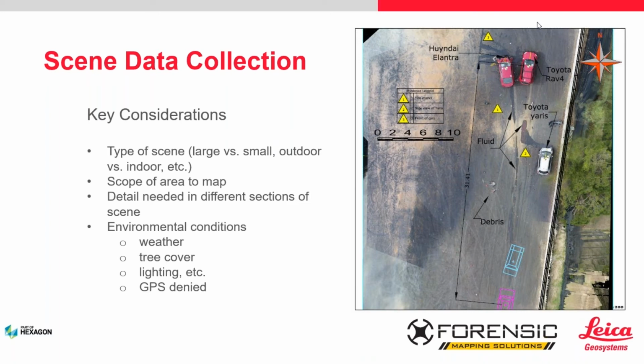And finally, GPS denied environments. All of the drones on their flight software are flying a flight plan that is pushed up to the drone, and it needs GPS to know where it's going and what positions it needs to be in. If you're in a GPS denied environment close to buildings, interference, one common one is a radio tower, high tension lines, cell phone towers, they will throw some interference either in your connection to the drone or potentially the GPS.